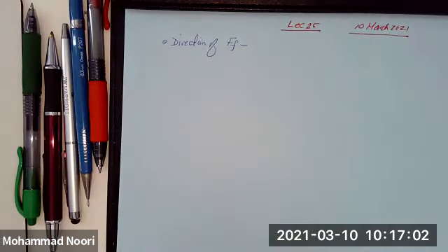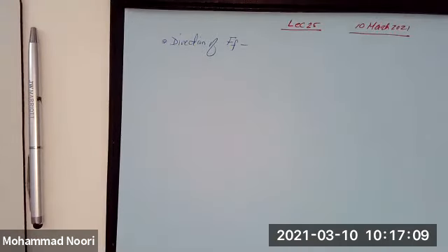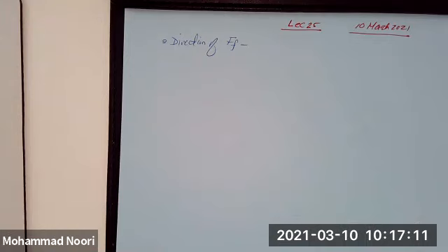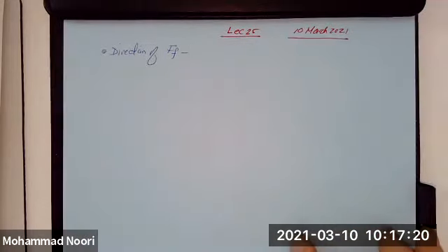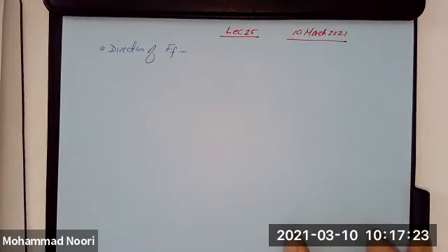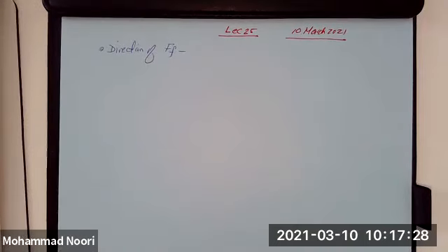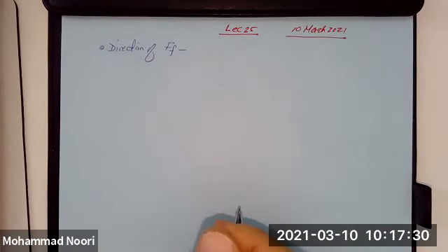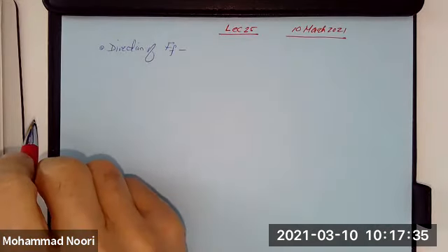Unlike the way you did the free body diagram in frame analysis, friction force is always opposite to the direction of motion. So you need to identify, based on the given information and the geometry of the problem, the potential direction of motion. Once you determine that, you know the force of friction is in the opposite direction, so you put it in the free body diagram.